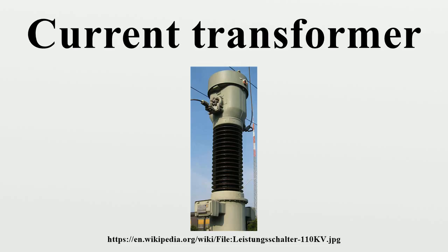The most basic current transformer comprises the secondary wound around the primary conductor, but typically current transformers consist of a silicon steel ring core wound with many turns of copper wire as shown in the right illustration. The conductor carrying the primary current is then passed through the ring. The CT's primary therefore consists of a single turn.